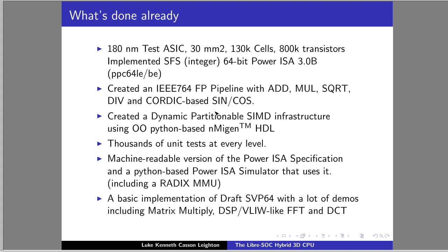The other way is to actually design your HDL explicitly so that it's subdivided down, so that even the most basic add operation has a hyper-specialist ALU, which explicitly opens up the gates between the add partitions and basically uses carry rollover between the eight. Usually, your base unit would be eight-bit adds, and you have a carry rollover.